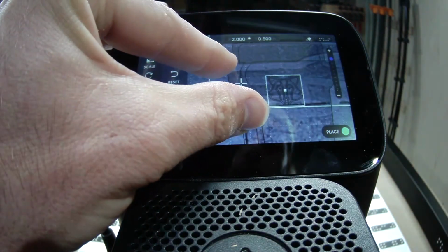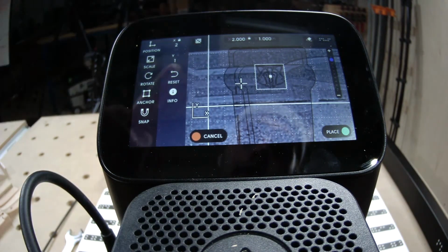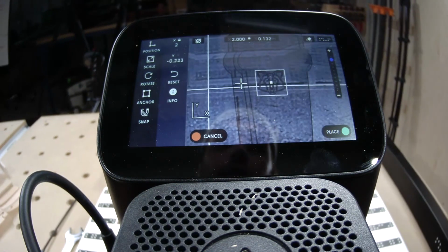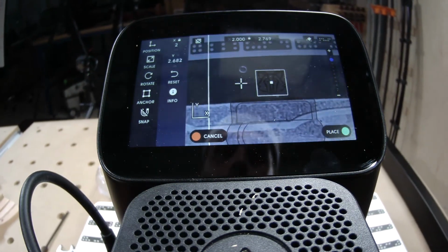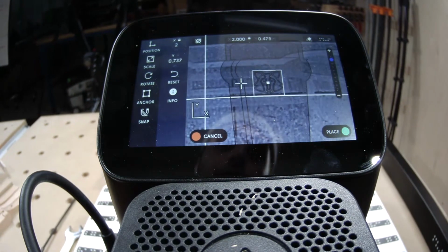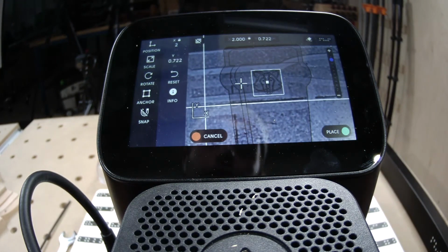So I'm going to go over here, and we're going to take it one step further. We're going to turn the grid off. So when I turn the grid off here, it's still locked in that one axis, but now it's free floating in the other. So if I want to put it right here, because I visually like how that looks, or lower, it's not going to snap just to the axes, and I can put it exactly where I want.